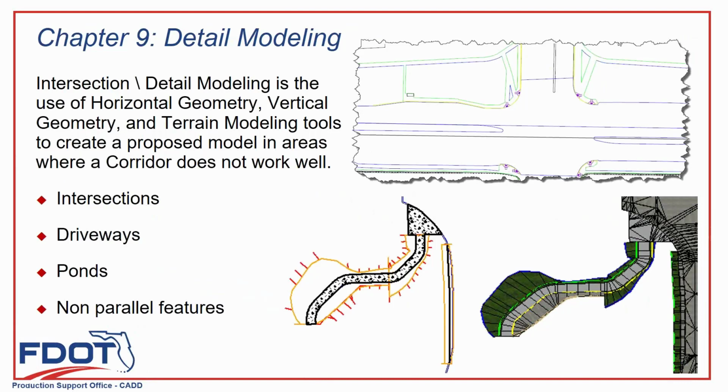So those are some techniques where you can take a slope and say, look for this other corridor and find the place where it meets this component 3 feet down from the top of that point. And it'll just search until it finds it and it varies that slope. That's one way to do it. You can do all those kinds of sophisticated things. So that's target aliasing.